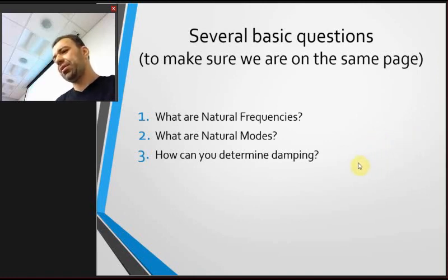So the answer is damping is probably the most elusive quantity. It can be determined only by test, or inferred from previous experience. But the real damping of your current structure can be determined by test only.